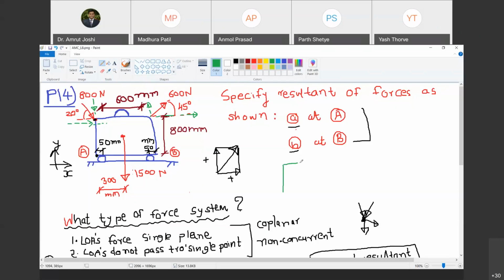देखो, for your ease I will draw the briefcase here. This is the vertical component of the 600 Newton force. So what kind of moment does it produce about A? Anti-clockwise. Do you agree with me? Yes, sir. So therefore, what should I write? 600 sine 45. This component is 600 sine 45.